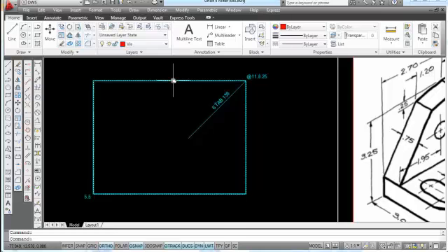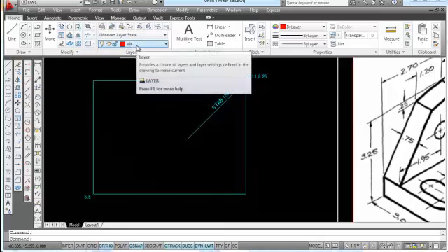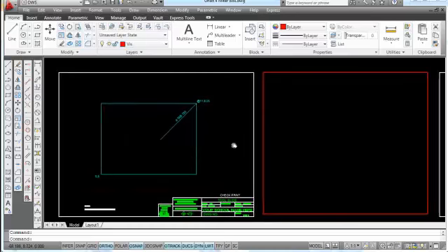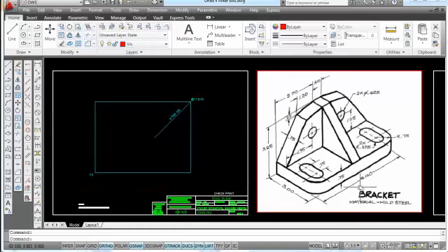One other hint here is that I made a layer called miter, and I put this rectangle and the line onto the miter layer. But right now I have the visible layer, or what I have called the viz layer, set to be my current layer. Alright, so let's look at this object. The front view of this object would be 6 inches wide by 3.25 inches tall. And so I'm going to add that into my drawing, into my miter box here with the rectangle command.